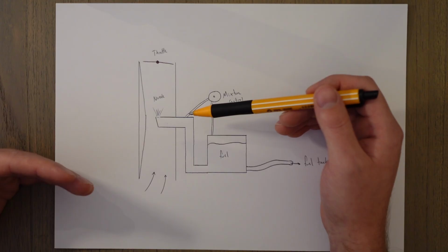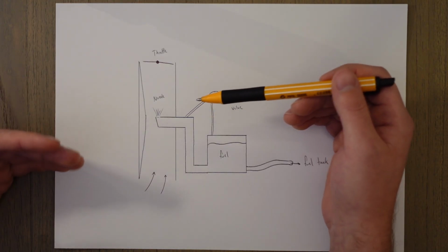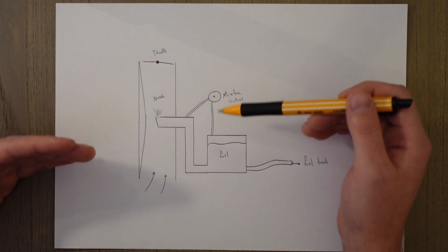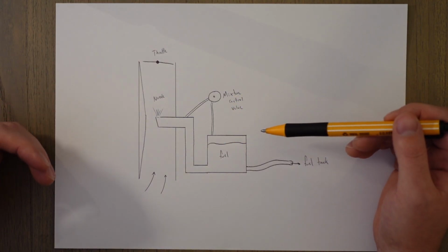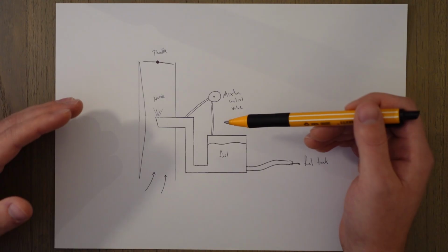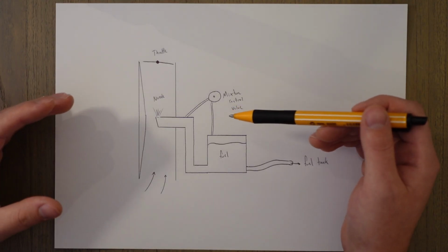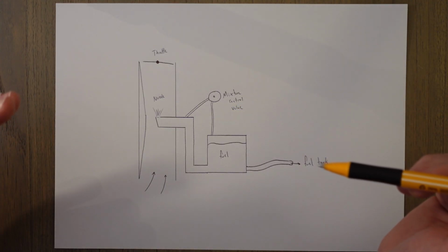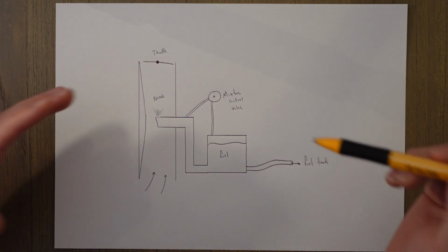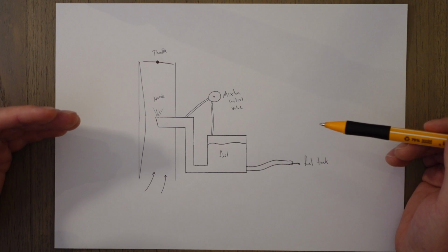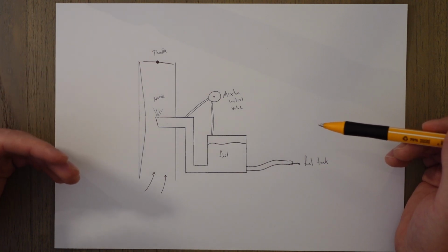Then if we want to draw less fuel up, we can reduce the pressure in the chamber, and that's a lower pressure differential. There are various other components in a carburetor which will improve the performance that would be useful to know, but I'm not going to cover in this class. I would encourage you to go and look at carburetor videos for more detail.